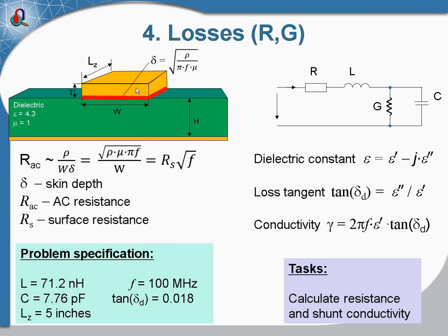It depends on frequency. At high frequency, the skin effect, which is shown in red, manifests itself. At low frequency, the resistance and inductance assume DC values, but as frequency increases, the cross-sectional current distribution in the transmission line becomes non-uniform and moves to the exterior of the conductor.